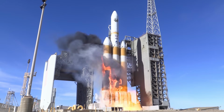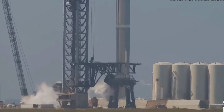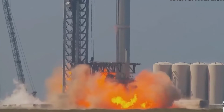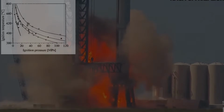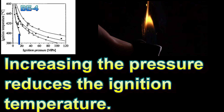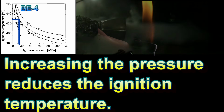The loud boom under the Starship means ignition might have occurred in one of the engine bells, creating a contained explosion at this location which spread to the rest of the gas. Here you see some graphs showing the ignition temperature of methane related to its concentration and pressure. High pressure crams the molecules together and increases the chances they will react. It takes a lower temperature under high pressure to ignite a gas.